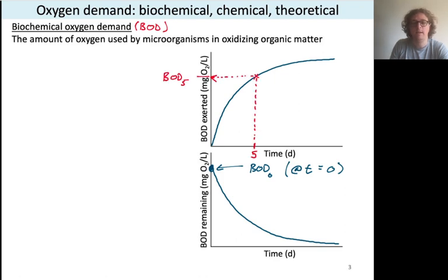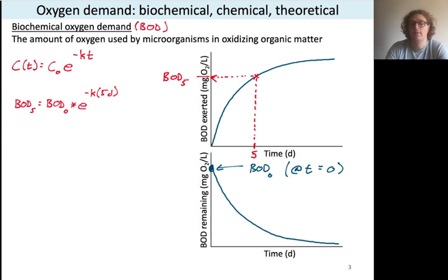Now, as we study BOD, one of the really important things that we'll measure is BOD5. And what this simply means is, if we think about a first-order reactive process taking place, BOD5 is telling us how much oxygen gets used within the first 5 days. Now, it's not that the first 5 days are critical in any way, shape, or form. It's that 5 days gives us enough transformation that we can project forward. So we could use that knowledge to find out how much BOD was there, what is the characteristic transformation rate, that first order coefficient K, for example.